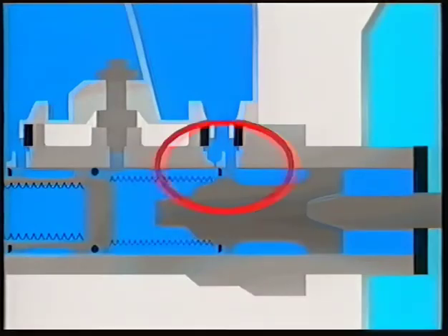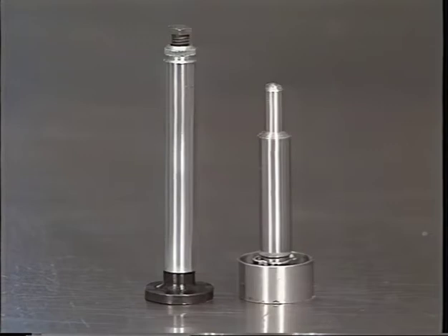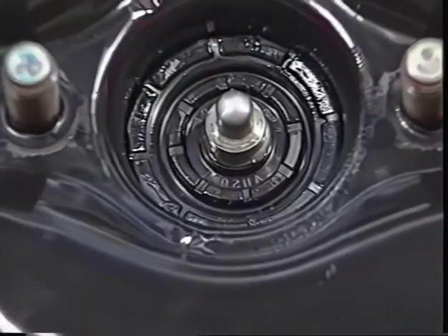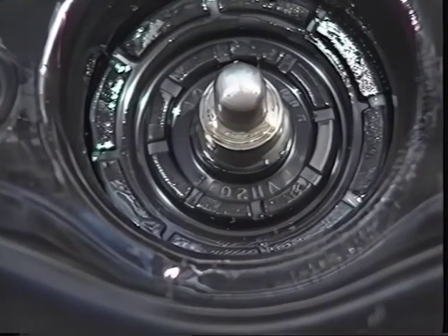We highlighted the fact that this adjustment was critical in placing the primary cup of the master cylinder in a position that left the compensating port just uncovered. It was explained that some booster output rods are adjustable whilst others are not, this latter type relying on genuine parts of the correct dimensions to provide the correct adjustment.